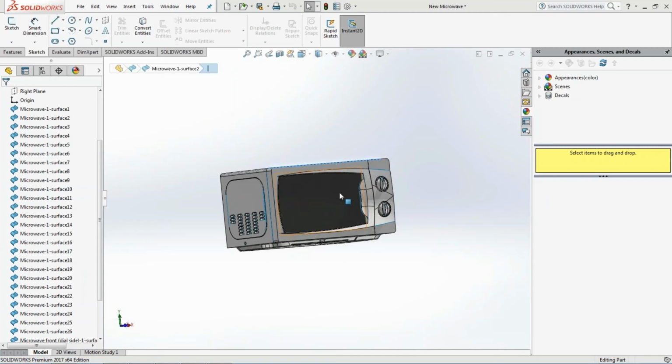Since we know the operating frequency, which is 2.45 gigahertz, the structure is going to handle all the modes at that frequency. So this is going to take care of that. And also because when you do EMI EMC testing at 1 meter, 3 meter, 5 meters in those approved labs, you care about the operating frequency, and you care about also the harmonics too.